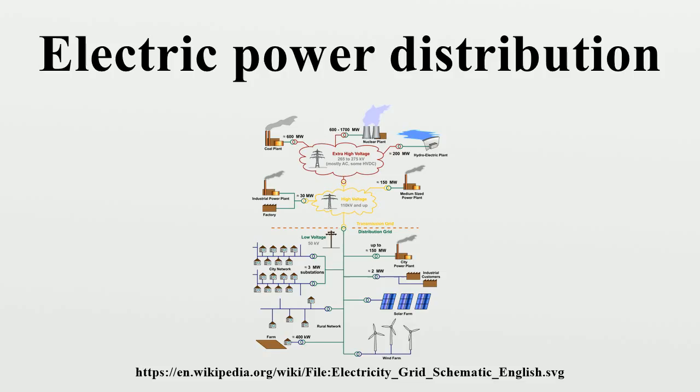Depending on the geographic density of customers, a single transformer may serve only one user or might have many individual customers. In very densely populated areas, secondary networks are used, with many distribution transformers feeding a grid at the utilization voltage. This improves reliability since many distribution transformers share the collected load.